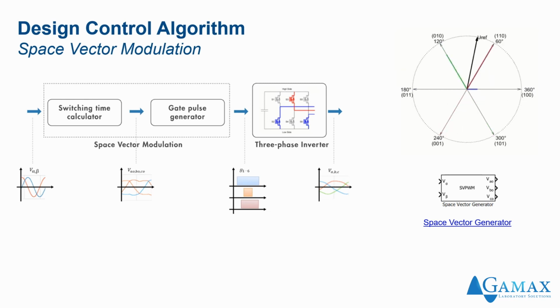So the space vector modulation eliminates the use of an inverse Clarke transformation. It operates on the reference voltage vector to generate appropriate gate signals for the inverter on every PWM period. So this technique basically calculates the on and off gating times based on the reference voltage vector, using the gating times to generate the double hump modulation waveforms, then also using the gating times to generate the appropriate gate pulses for the inverter switches.